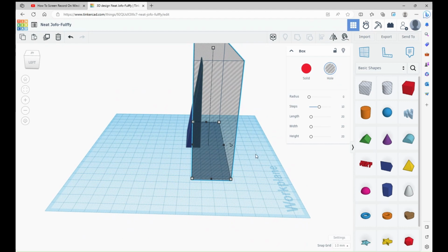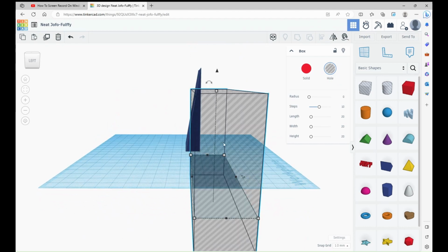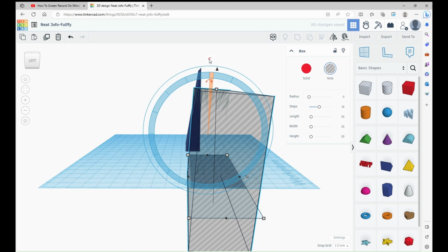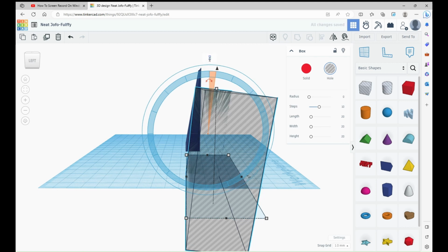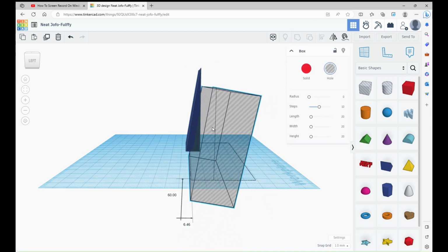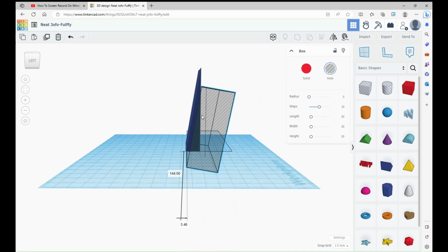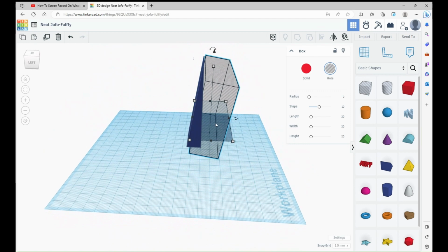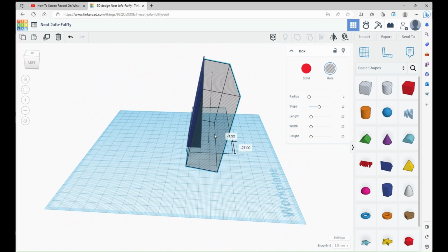And I don't want to remove all of this. I just want to shave off a bit. So you can actually rotate the portion that you want to have removed. You can see me rotating that transparent box, and that's going to be your subtract. Whatever is covered by that transparent area, the box or other shape, is going to be subtracted from the area that's going to be printed. So in this case, the blue triangle.